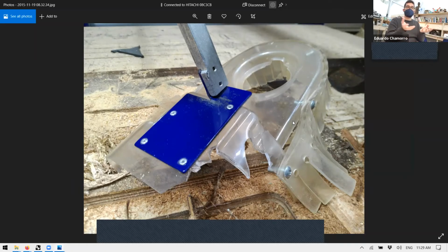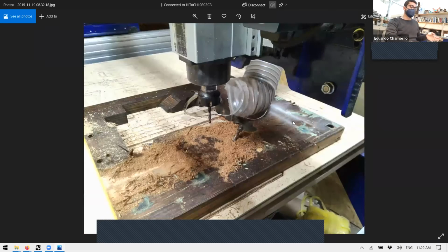Exactly. Those machines are meant to use big flat parts, not three-dimensional parts. For example, some of the machines that we use, like this CNC Stepcraft or these ShopBots, have this point and the motor slightly down. So you can actually reach higher three-dimensional movements without collisions. If you have a big area around your motor, you cannot make three-dimensional movements, or you need to disassemble the part to be able to make them.